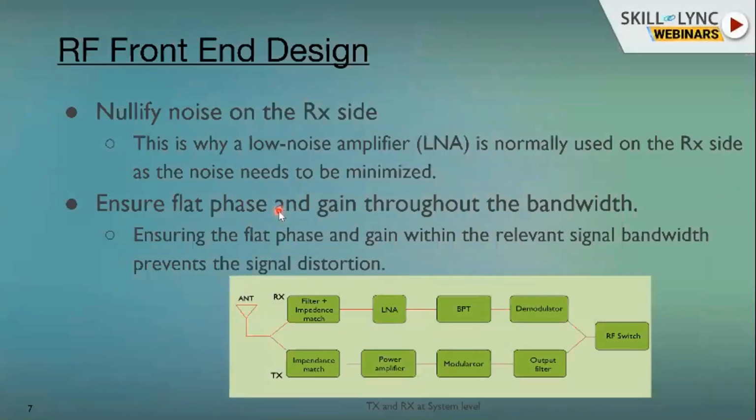if you go to the receiver side, you will try to nullify the noise. There will be distortion at the transmitter side and also at the receiver side. You are receiving noise, and that noise can be environmental noise as well as system noise. As I mentioned, these low noise amplifiers are active devices.